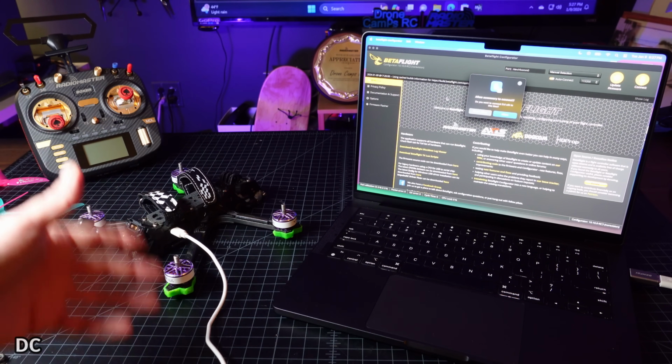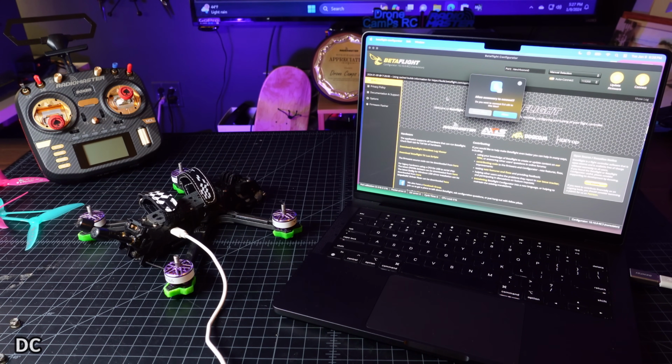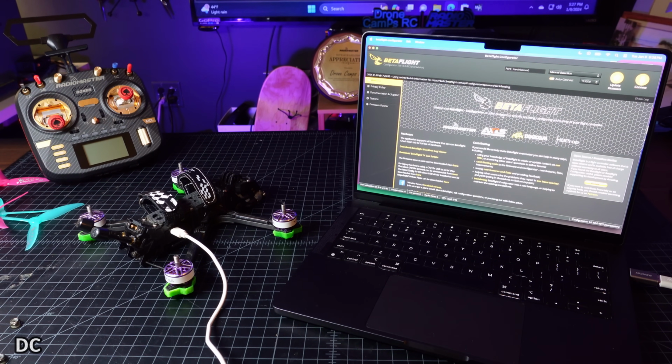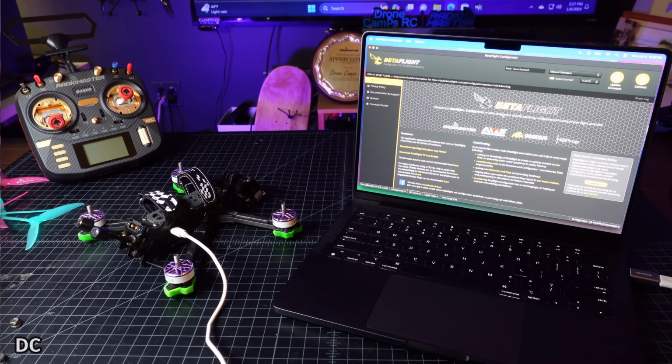Even inside Betaflight, if it's just a flight controller change or a mode change, sometimes the arm switch can happen on the bench and cause big problems. Now, Betaflight does have some safeguards in it that will not allow the motors to arm until you check a button. But even checked, sometimes I've cut my finger or had an accident or had a quad fly across the bench or try to hit me in the face. So there's a lot of things that could go wrong with the props on indoors. So I always used to say, little Johnny, take off your props indoors.